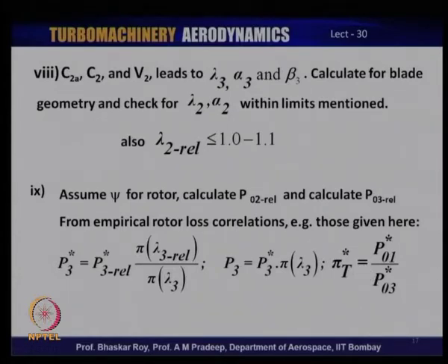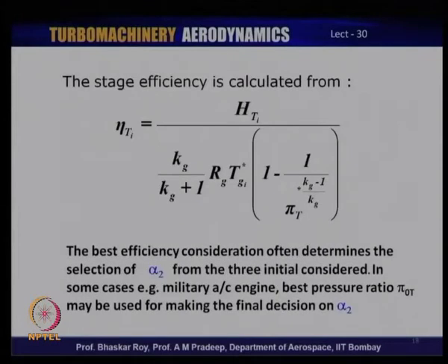Now, this gives us the pressure ratio across the turbine at various locations, and together it gives us the pressure ratio of the entire turbine. Now, next we can find the stage efficiency, which is indeed calculated from the work that is being done, and with reference to a large number of parameters that we have already used.